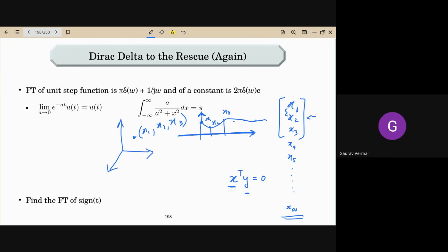If that is true, then you can say the signals are orthogonal. And in the scenario where the signals are not orthogonal, it means that there is some component of X that you can produce from Y. So there is some component of Y that is present in X. Not necessarily the entire signal, not necessarily that X should be simply some scaled version of Y, but there is some component. If you just take the inner product, X transpose Y is not equal to 0. Which means if you project that signal onto Y, you should be able to get some component of X.